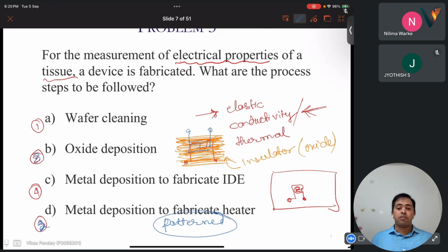That is using lithography. Sometimes when we are going for bigger dimensions, not less than 200, 300 microns, if something is more than 200 or 300 microns, we can even go for deposition directly using a shadow mask. Like we can have some steel or chromium mask which has cutouts. It is very similar to a lithography mask, but that is on a glass.